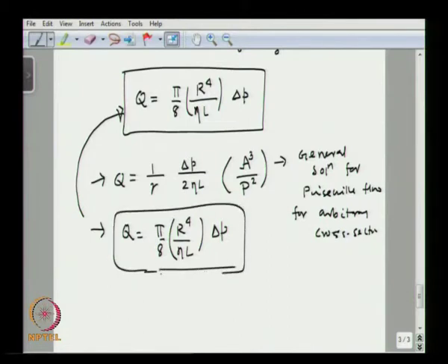Right. So, circular cross sections also have practical relevance in microfluidics. They can be fabricated in silicon wafers. If you do bulk micromachining with isotropic etching with solvent agitation, you would be able to produce circular channel cross sections. Actually, it is a semicircle that you will be able to produce, and if you bond two such semicircle channels, you will be able to generate circular channel cross sections.